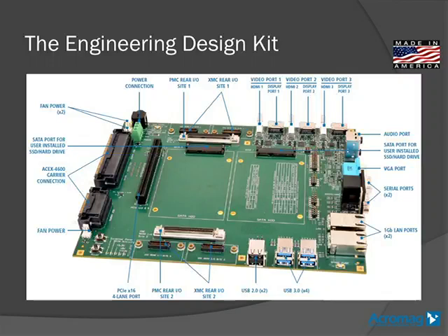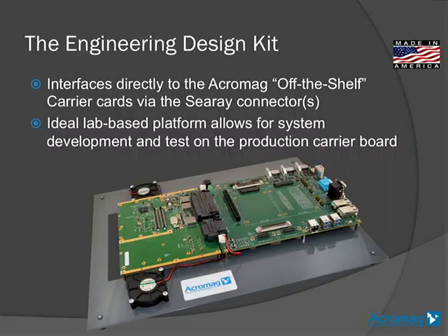Okay, so we'll go one step further. This interface connects directly to the off-the-shelf carrier cards via the C-Ray connector. So you can see the interconnect here. And this entire unit is available with the EDK, the steel plate, and 2 fans. The purpose of the fans is to blow air onto whatever PMC or XMC you may have on the flip side of these carriers. In some cases, we've actually tested this with 2 Virtex 6s, and the fans are extremely beneficial.